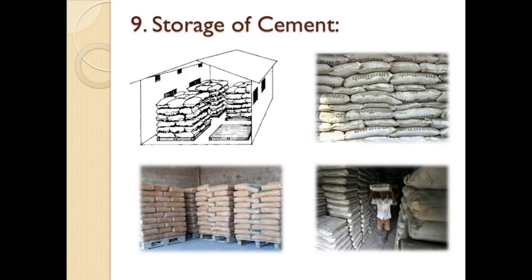high humidity, as it can rapidly lose its strength and turn into lumps, rendering it unsuitable for use. So during the monsoon, we know every year there is considerable damage to cement due to incorrect storage and transportation. Therefore, it is important to have a proper storage arrangement at the consumer's end. So what are the precautions we have to take for the storage of cement? Let us see one by one.